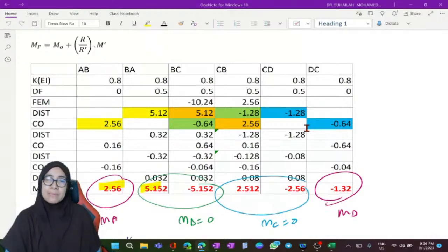But remember, in table number 1, we only consider external loading. We have to have table number 2 because we do not know the value of the delta which comes from sidesway. That's the difference between frame and beam, because in a beam, the delta belongs to support settlement, and support settlement is always given in the question.